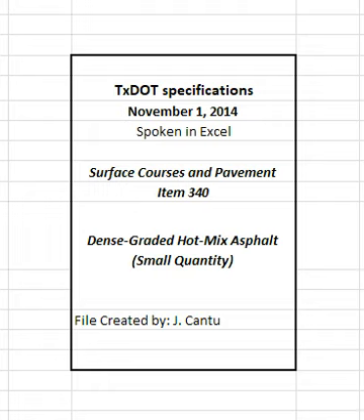Add sand meeting the requirements of Table 1 and Table 2, or fine RAP, to RAS stockpiles if needed to keep the processed material workable. Any stockpile that contains RAS will be considered a RAS stockpile and be limited to no more than 5% of the HMA mixture in accordance with Table 4.